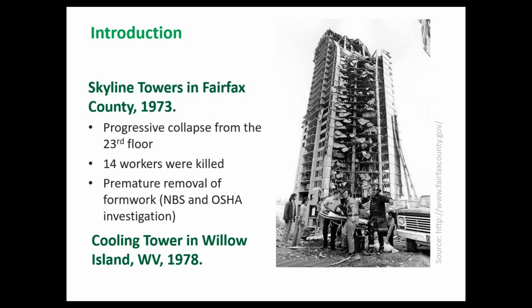And these investigations that started after these incidents led to the development and standardization and documentation of accurate methods that can be used in the field to monitor concrete strength. And I'll get into the details of why the break test is not really sufficient in several cases, and how other methods can be used to accurately monitor strength development at the early stages of construction.